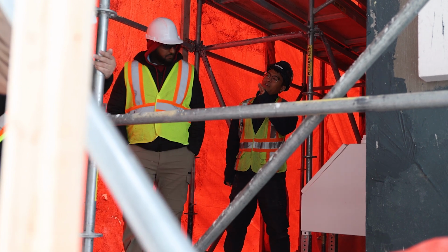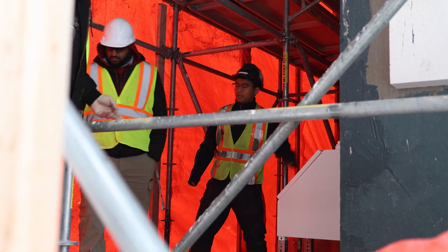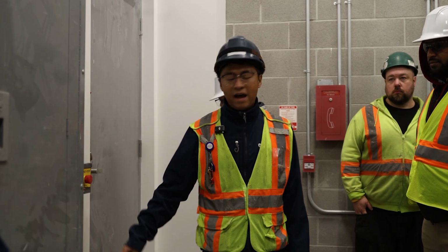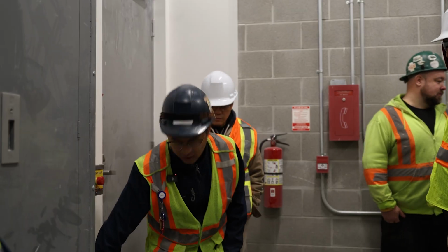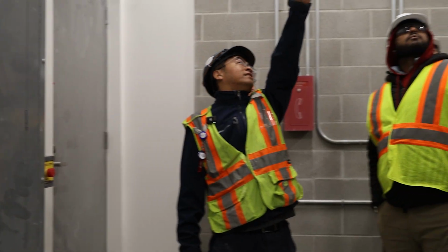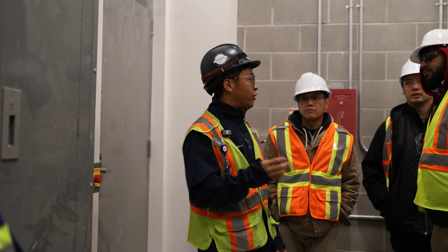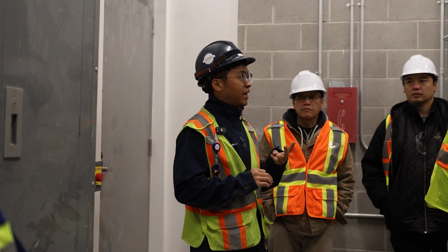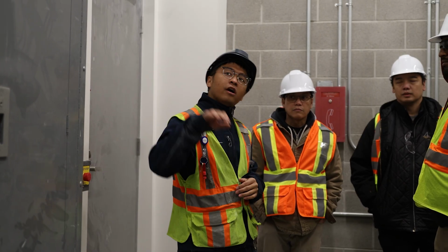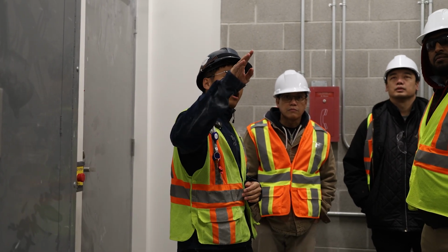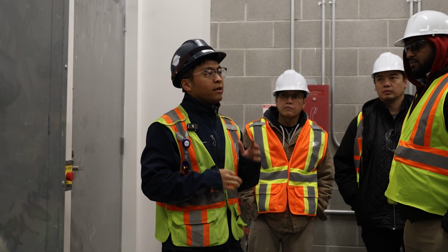And we also have a CO and NO2 sensor in the generator room. I will show you where they are. We have two sensors that BMS is monitoring in this room. It's the CO sensor right here and the NO2 sensor over there. So BMS will monitor the CO and NO2 level. There are two stages of alarm levels. In the first stage, the outside damper and the exhaust damper will fully open to purge the air in the generator room. That's the first stage.